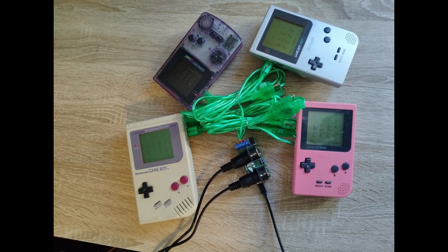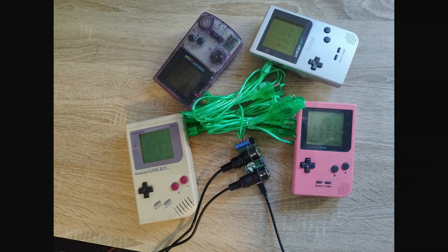Sadly, there's not much that we can do about this fact either. Since each Game Boy only has 4 sound generators, there's no way that we can simultaneously play 16 MIDI notes with fewer than 4 Game Boys. Similarly, since we need to run a piece of software to interpret and translate those MIDI signals on the GameLink port, there's also no way for us to avoid the cost of buying 4 flash cards. Really, the only point of attack for any cost reduction measures would therefore sit at the MIDI interface.